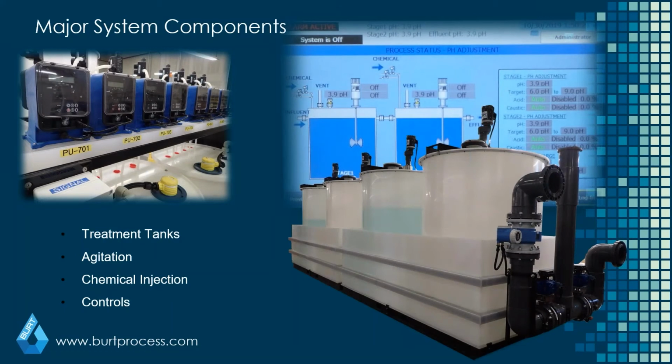But as a result, there's a lot that goes into these systems, at least from a size perspective. You have treatment tanks, agitation, chemical injection, controls, and the standard residency time for a pH neutralization system is 20 to 30 minutes.